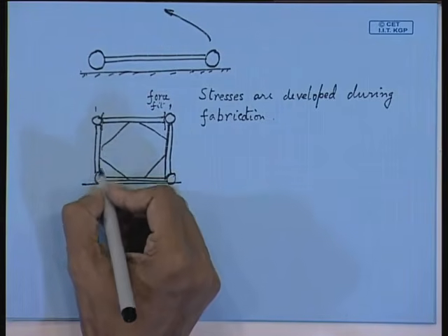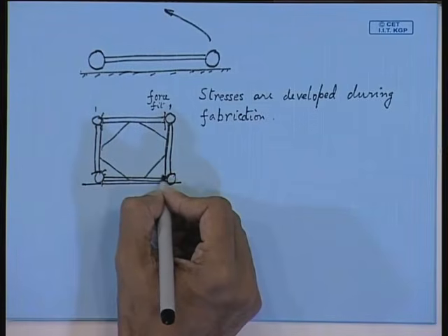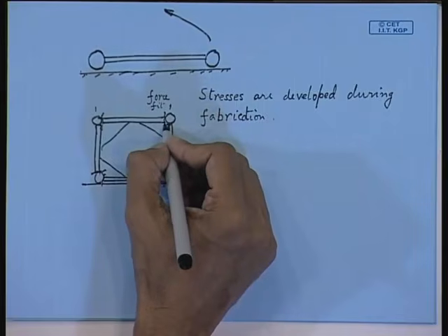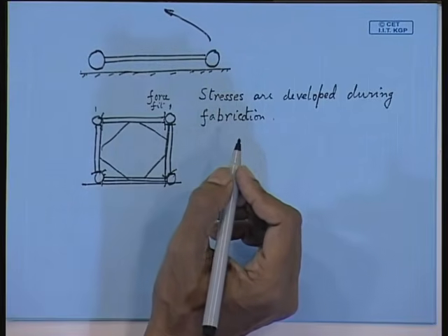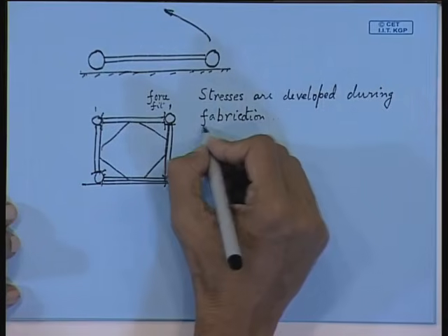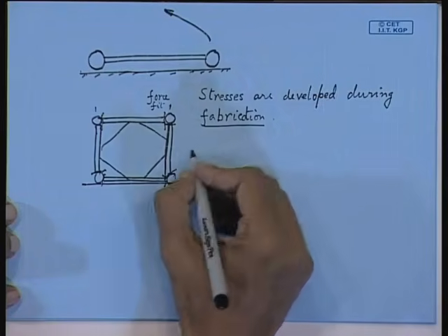These are the favorable spots for what is called stress concentrations. So, a jacket is normally a very huge structure, and if you are not very careful during the fabrication stage, this leads to stress concentrations developing at the joint.